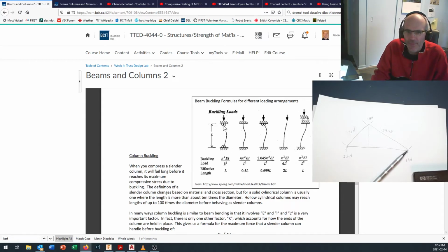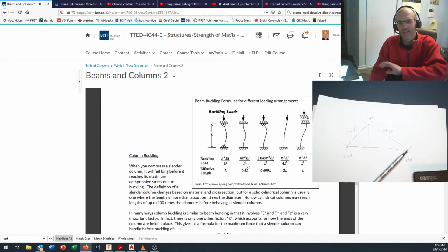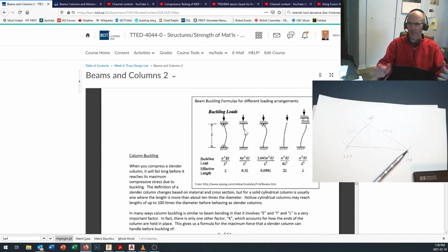And so here you can see pinned at both ends. This is what we were doing in our compression testing lab, and you can see the shape where that bends out, just like what we were looking at. But here you can see where they're fixed at both ends, and there has to be a 90-degree joint right in here. So that's kind of like if you buried this end in here. So if you drilled a hole into your loading platform and your loading platform was perfectly rigid and it was just coming straight down, this part can't bend or flex in there. That shortens the overall flexing distance. And if you look at the buckling load formula on here, it goes from pi squared EI over L squared to 4 pi squared EI over L squared. So since pi squared EI over L squared is the same in both equations, you can forget about all the fancy stuff in here and you can just say, wow, this one is 4 times as strong.